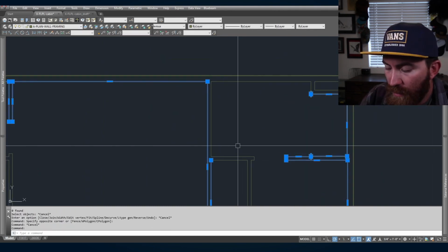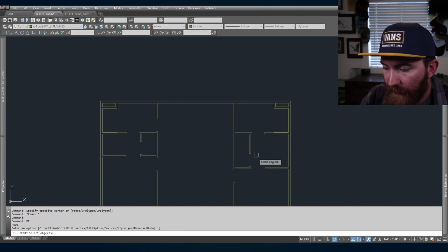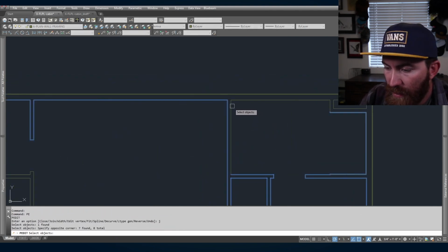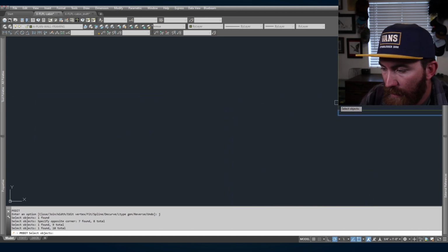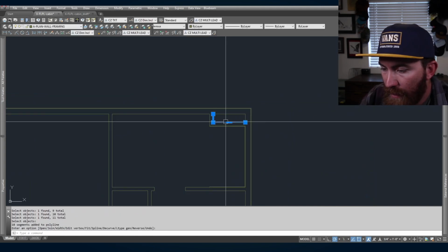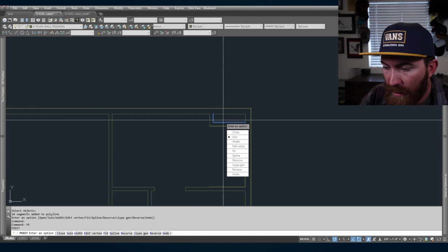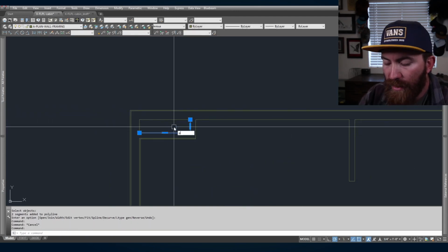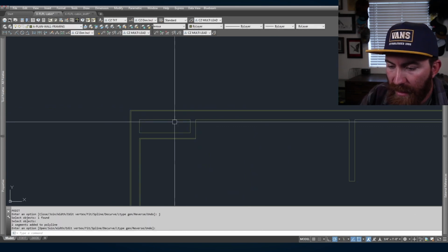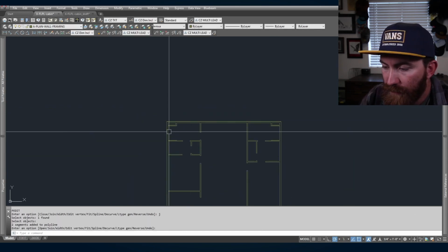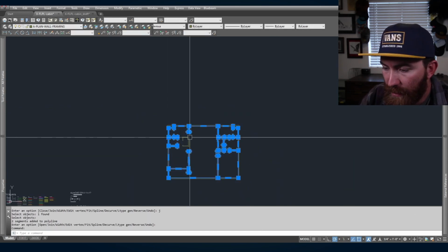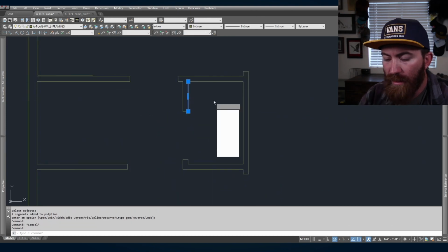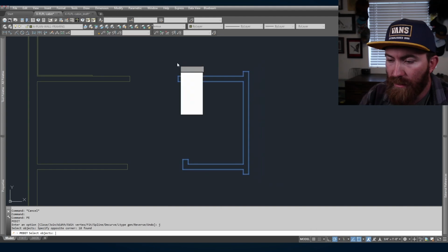Okay, so it does go all the way to that. Poly edit. This, I like to select it. There we go, so I know what's selected before. And to here, boom. We're going to just do this. Poly edit, join that. Makes a box. Poly edit, join that. Makes a box. I think I'm good. Okay, nope. I gotta do this one. Poly edit, join, select it all.